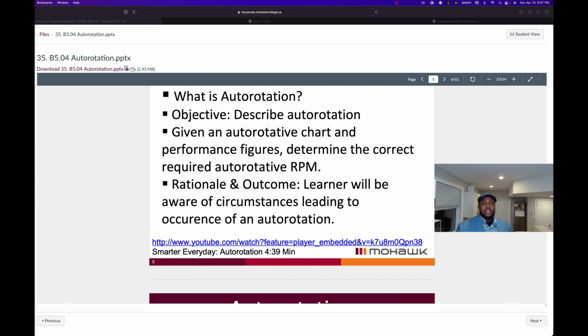The other regions, like the driving region, are also affected in a similar manner as the stall region. The driven region on the retreating side is reduced, and this impacts flight by producing a sort of rolling effect on the helicopter.